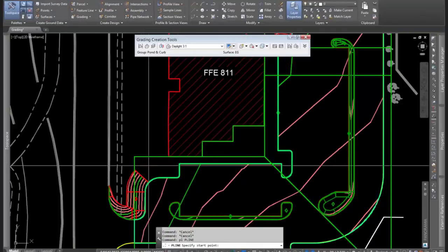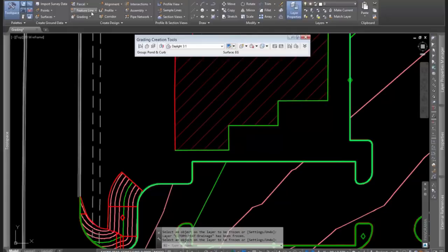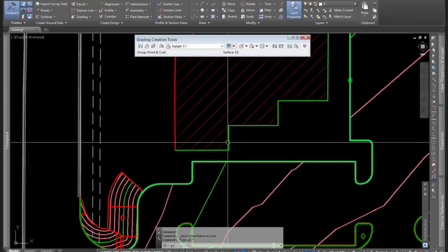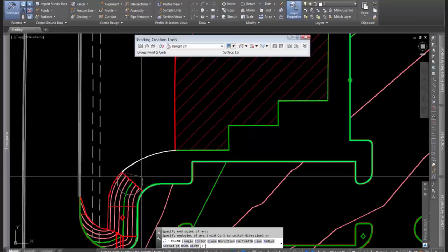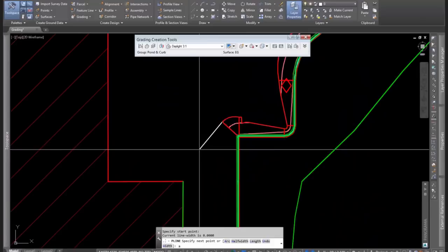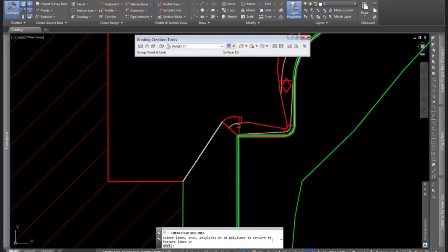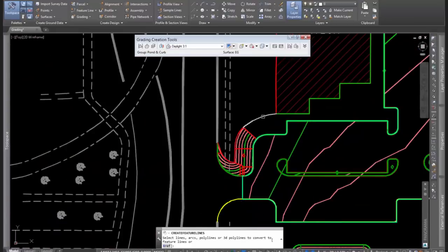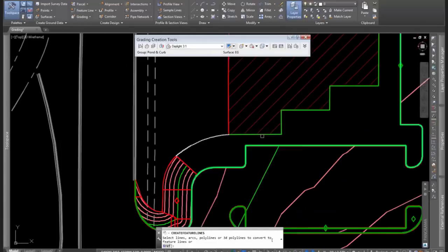Okay, if I draw a couple other feature lines, again starting with polylines, a polyline here, and another polyline here. And we turn these into feature lines, and we pull elevations from existing. Because after all, existing is right there. That's where this daylight grading was. This building feature line, that's matching to an existing right there. So we just kind of need to connect these two points, and these aren't constant slopes in here.